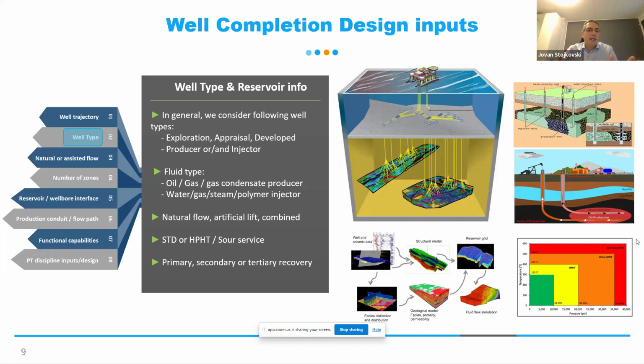If you are going, let's say, for the standard completion, medium to low, shallow wells, then it will be a little bit easier. But if you have very challenging wells, where we have HPHT wells, high pressure, high temperature, a sour service environment, plus if we need any kind of sand control and stimulation job, you can see how much you are going up with your details. In fact, this complicates your design. And in the end, you just need to pay attention to the details.